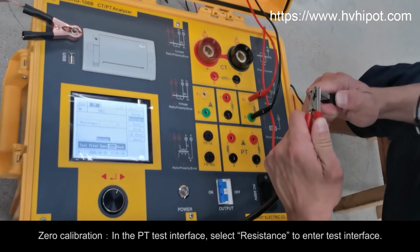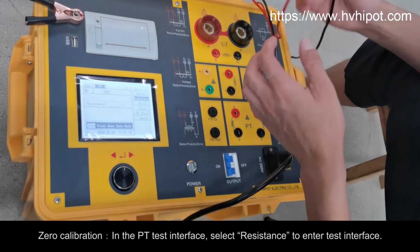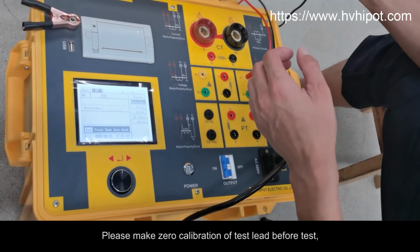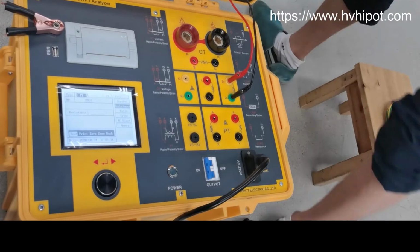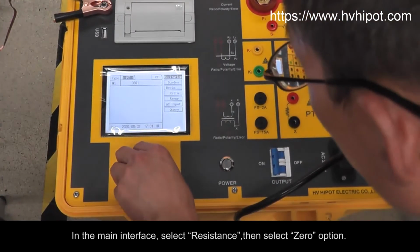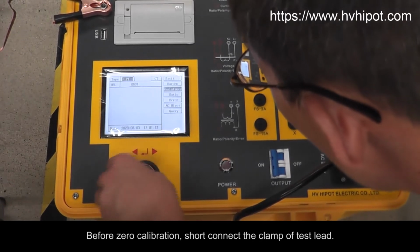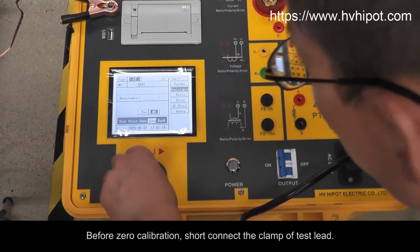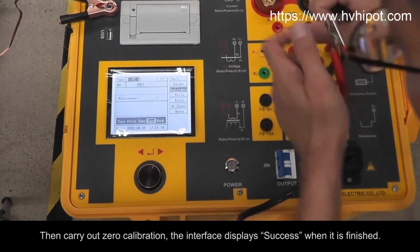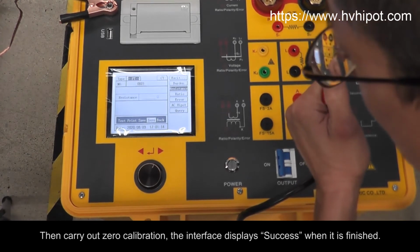Zero calibration. In the PT test interface, select resistance to enter test interface. Please make zero calibration of test lead before test. In the main interface, select resistance, then select zero option. Before zero calibration, short connect the clamp of test lead. Then carry out zero calibration. The interface displays success when it is finished.